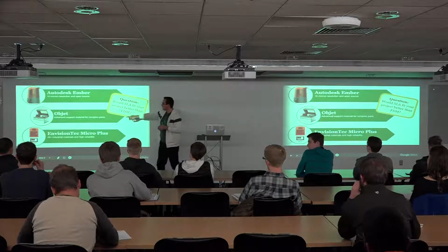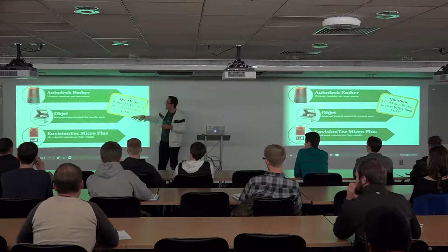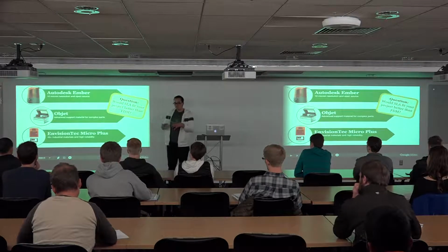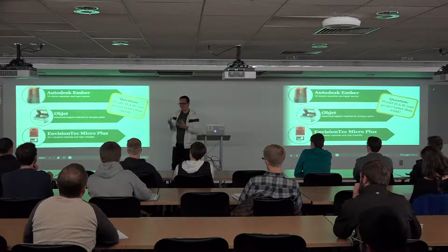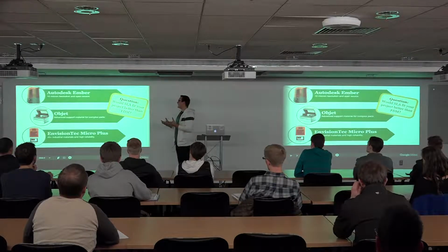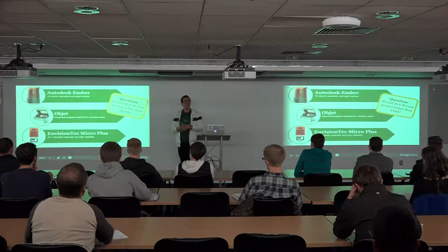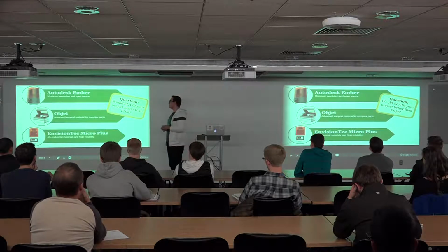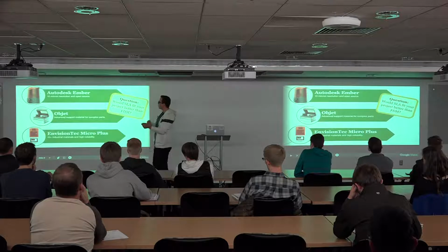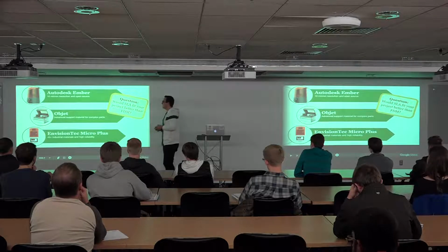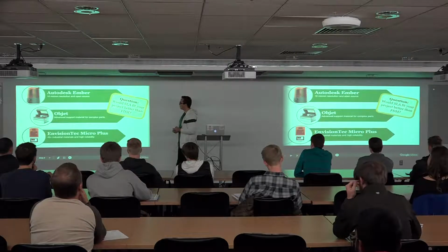The Objet is really cool because it has an advanced support material, and it basically encases your whole print in support material. So if you have overhangs and complex geometries, you can get those really simply, and then you just pressure wash your part to get all that support material off. It's kind of like a soft, easily removable polymer.